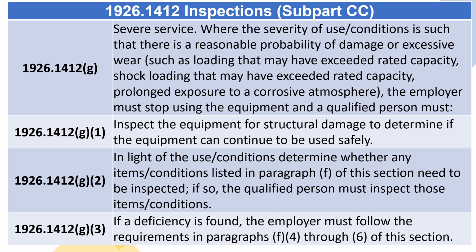1926.1412 G. Severe service. Where the severity of use or conditions is such that there is a reasonable probability of damage or excessive wear, such as loading that may have exceeded rated capacity, shock loading that may have exceeded rated capacity, or prolonged exposure to a corrosive atmosphere, the employer must stop using the equipment and a qualified person must, per G1 through G3, inspect the equipment for structural damage to determine if the equipment can continue to be used safely.